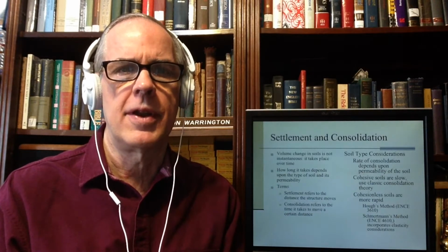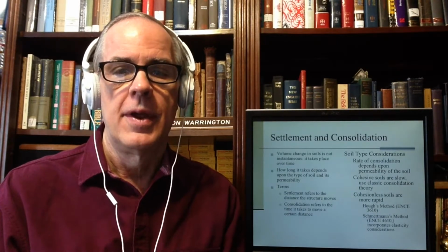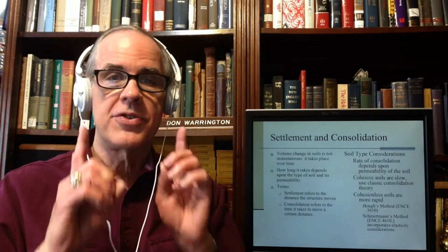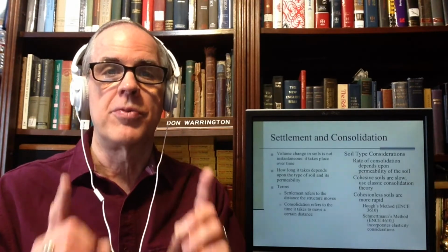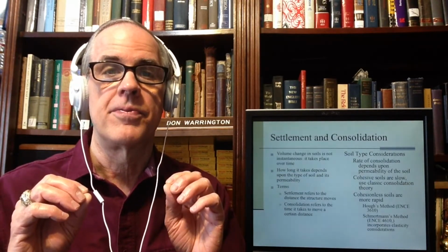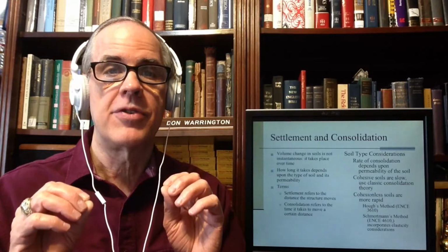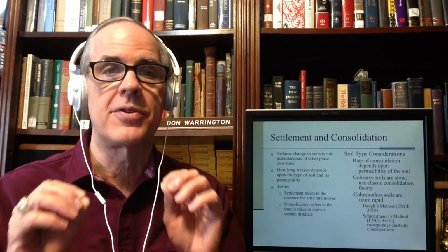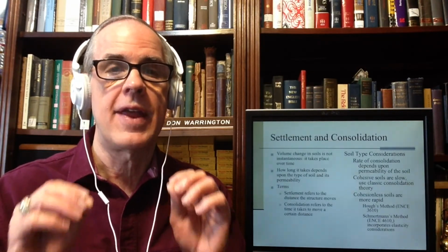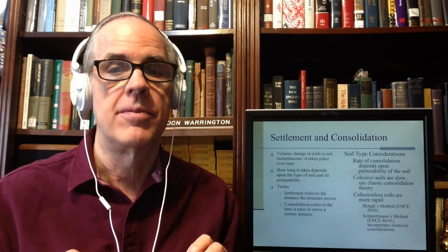Settlement and consolidation. Volume changes in soils are not instantaneous. They take place over time. The question is how much time. It depends upon the soil and its permeability. Primarily its permeability is the big variable. Now, let's stop and define two terms. We're going to come back to this. Settlement and consolidation describe the same thing, but they describe it in a different way, and they answer different questions.